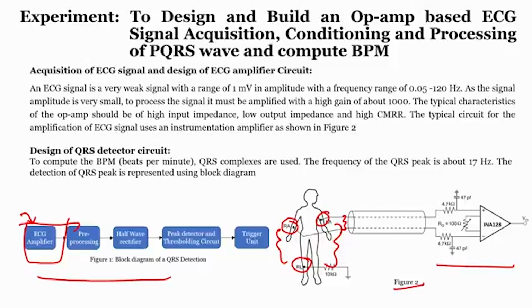Of course, an instrumentation amplifier uses a differential amplifier inside, but we cannot go with a plain differential amplifier because it has very low CMRR, and moreover the input impedance of an instrumentation amplifier is much higher. The reason is that the input is directly connected to the non-inverting terminal of an op amp, because the instrumentation amplifier is made up of a 3 op amp based circuit.